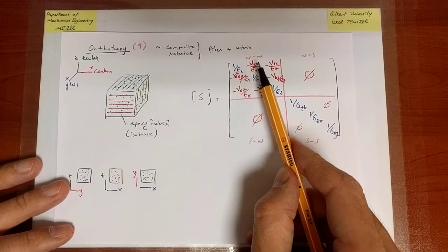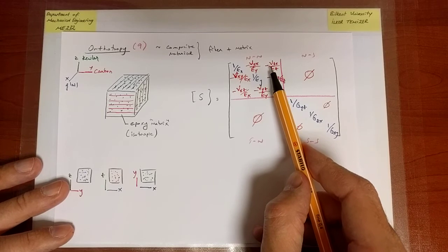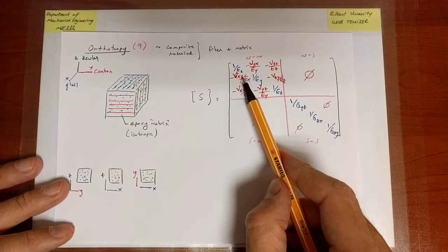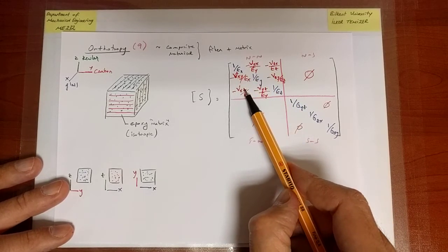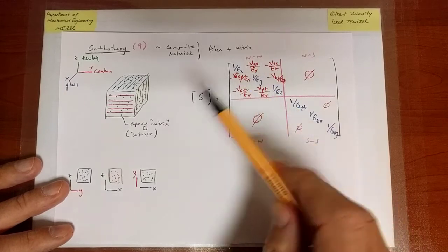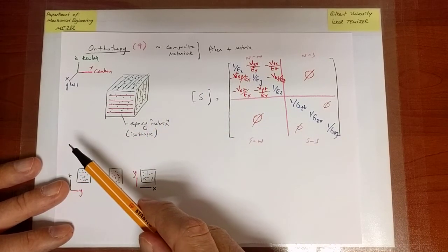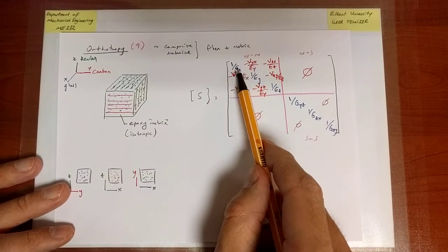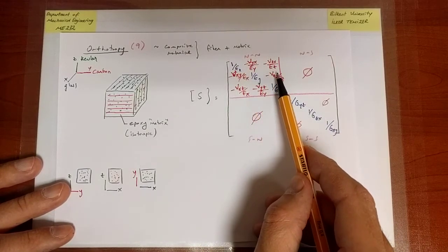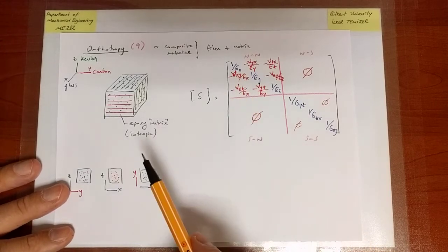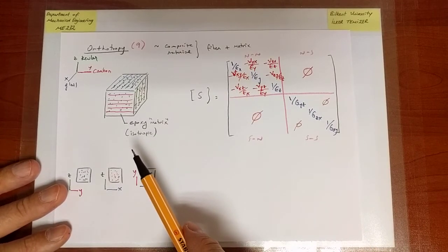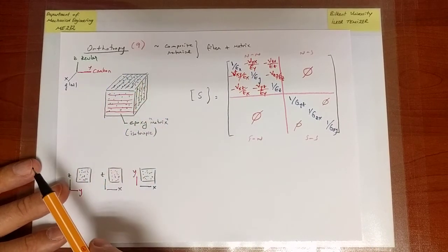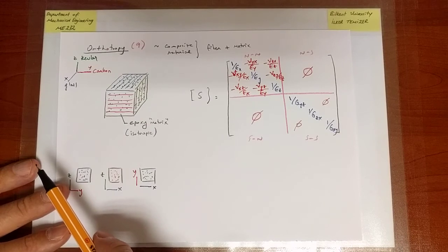And I see nu yx and nu zx, or I see nu xy and nu yx, nu xz and nu zx, right? So terms switch, right? So my question is, well, are these all independent from each other? So in other words, do I have 6 plus 1, 2, 3, 4, 5, 6, a total of 12 independent constants? It contradicts what I said earlier. And so the question is, well, where am I making a mistake?